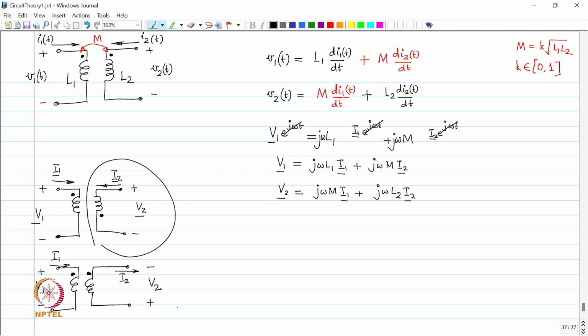So, you had earlier V 1 is equal to j omega L 1 times I 1 plus j omega m times minus I 2. Okay.